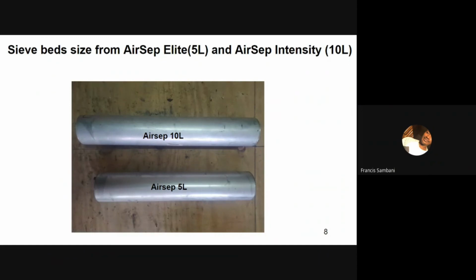So we've also done extensive experimentation looking at the differences in purity across various cycle times with and without degradation. To a large degree, the optimal configuration does not really change between the concentrator models when sodium or lithium-based zeolite is used.